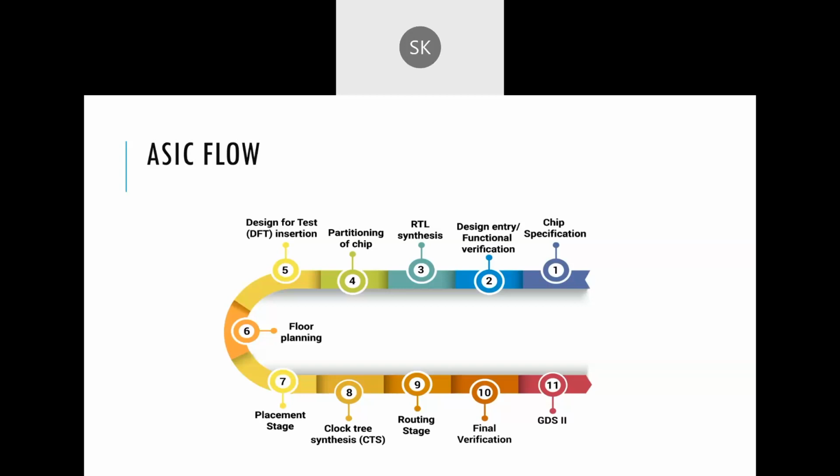On a SoC, on a chip, we have so many components. We can't just place any component here and there. There should be a proper way, a proper data path, and proper communication between the components, for reducing the wire delay and reducing the noise. So we should have a proper floor planning, so that it is efficient and delivers a good speed.